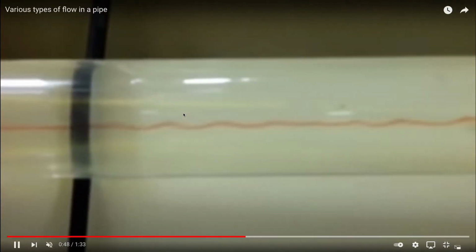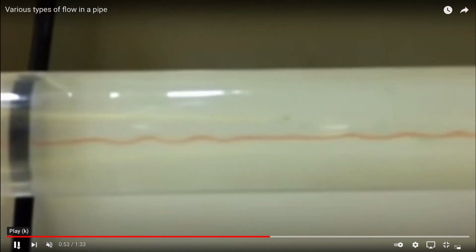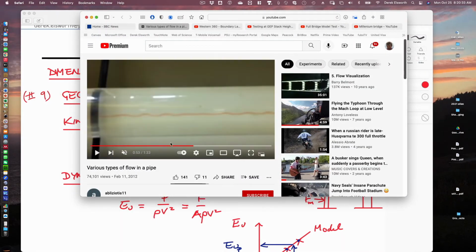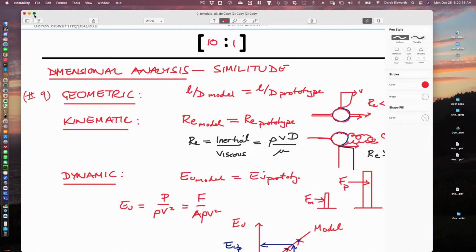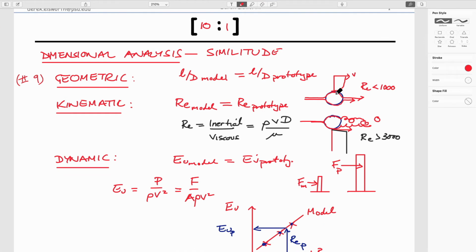But the diameter of the tube is another dimension that's intrinsic to this system, which would seem to make more sense. And so, going back to our discussion on these equations, if you look at, say, flow around a sphere, an external flow, with a Reynolds number less than about 1,000, what you tend to get is that all the flow lines around that sphere basically parallel each other, as you could imagine if you drew a kind of flow. You could imagine this being the case.